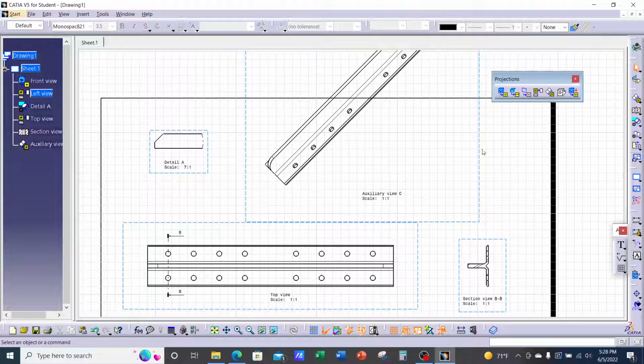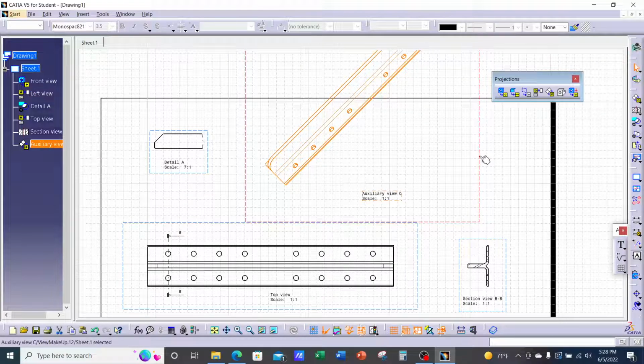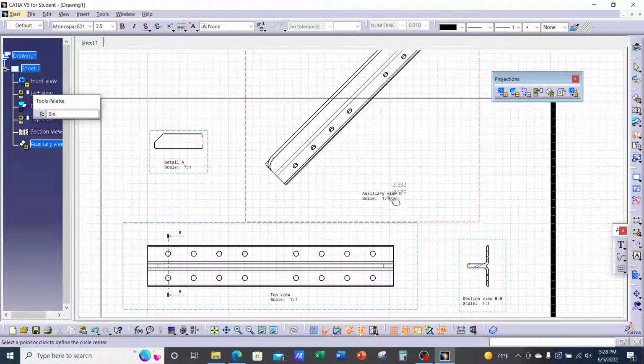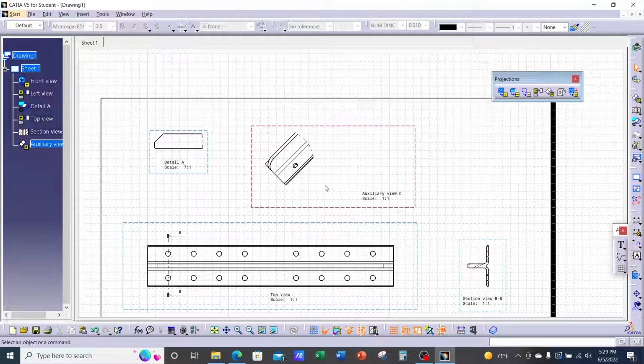First let's activate the view. Let's double click. Then we're going to clip. I'm just going to aim somewhere near the center of the portion we want to keep. I'll click. That's good enough, we'll just eyeball it. Click. And it'll break off the portion you don't want.